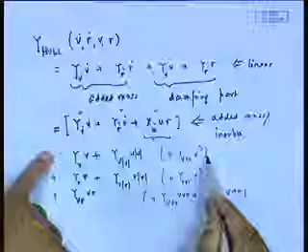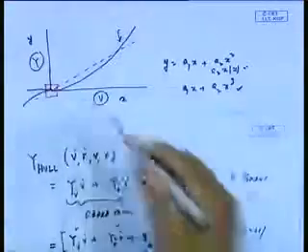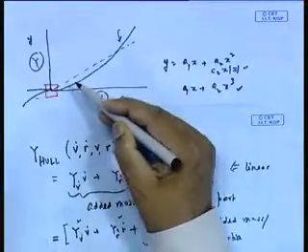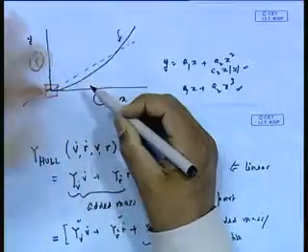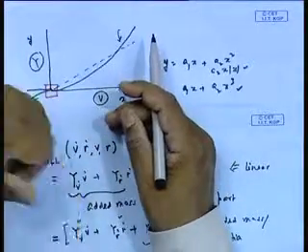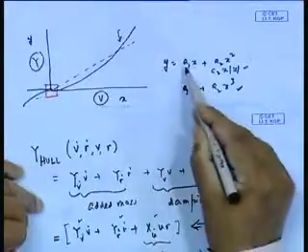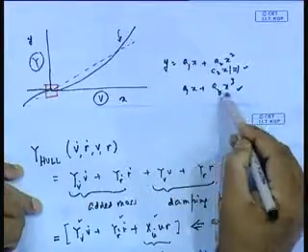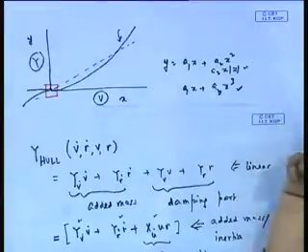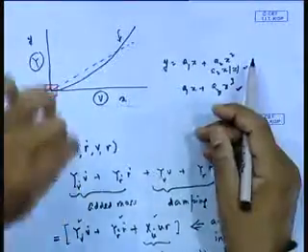See, first you have to model with certain coefficients. Basically, I have a curve, I have to fit a curve with some assumed polynomial, that is my model, and then my next job is to find what the coefficients for the polynomial are, like what is my a1, a2, or a1, a2, a3, depending on which one I choose. So, first I have to assume a model, then I have to find out the coefficients for the model. Remember, these are coupled, there is nothing like nonlinear derivatives. It depends on which nonlinear coefficient you have used to model the force, and that is the one you have to determine. Now, you see here, I just show you a possible model, this is like that.